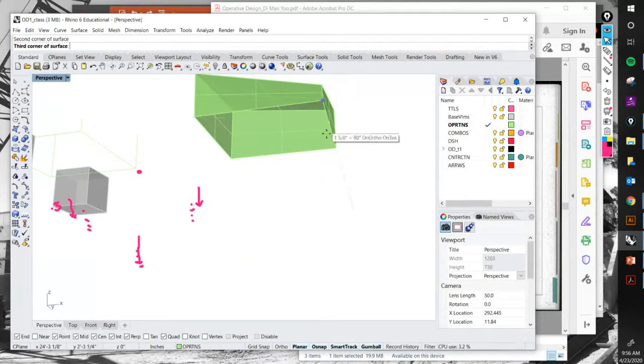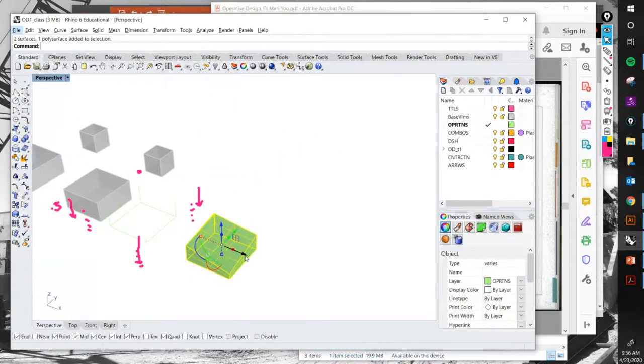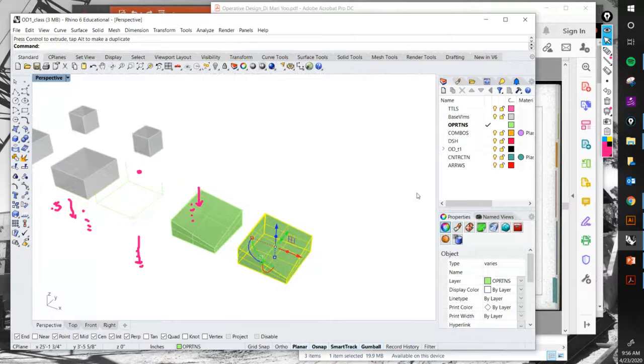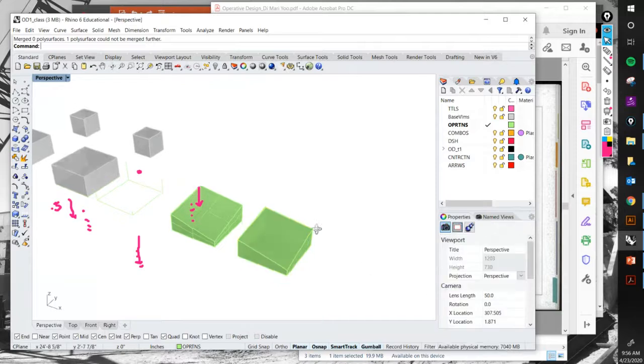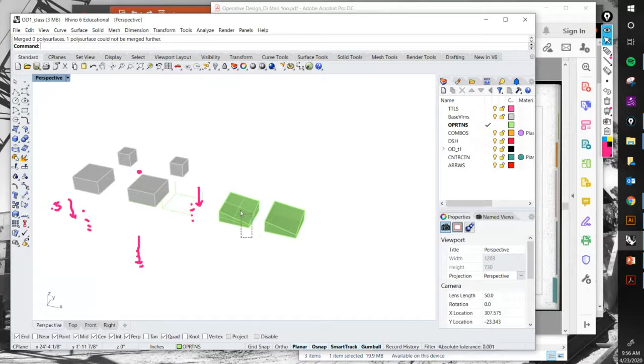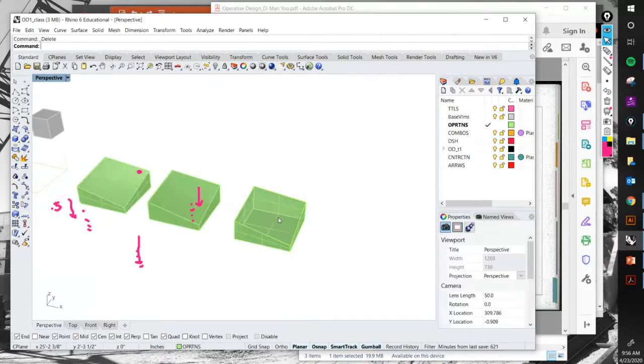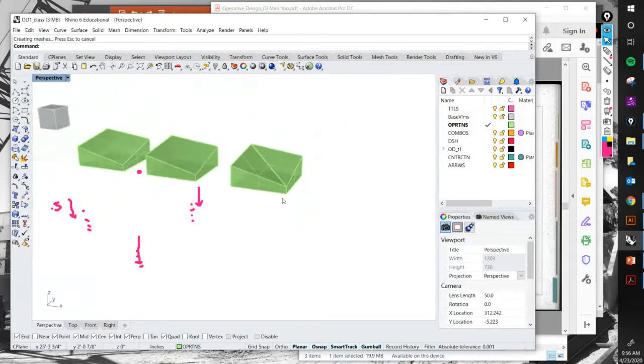And I can then come over here and do this guy right there. I can select that, copy it right here, and then I can join, merge all the faces, and get rid of the ISO curves, and I have that right there. But I would actually argue that that's not quite right. I would maybe argue that perhaps even better would be to split that half portion into two triangles, like that.